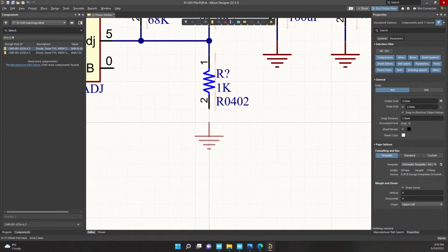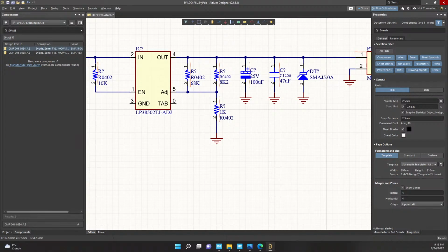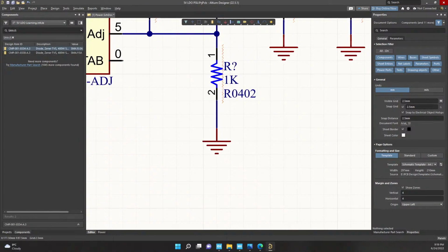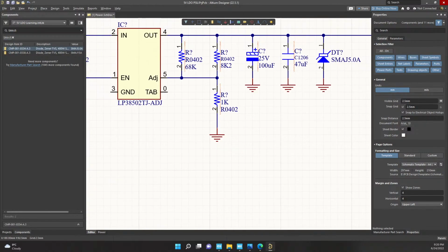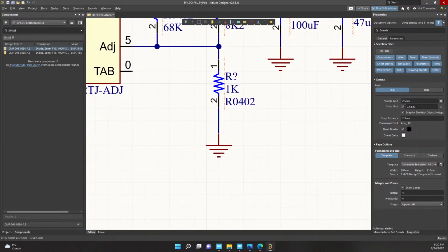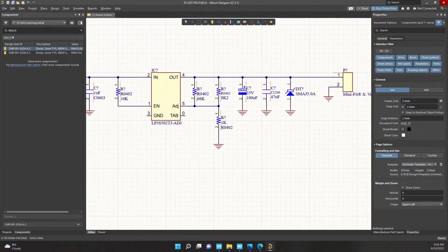But if it doesn't make a connection, what you can do is press Control down and move. Oh, mine is inverted. Okay, I see. The setting is inverted. Normally, you move it, it connects, but if you move it down, it disconnects. But if you press the Control key down, it keeps the connection. In this case, we see that it's keeping the connection even if you move it down, which is perfect. This is what we want. Or you can just, not be fancy, and add a wire normally.